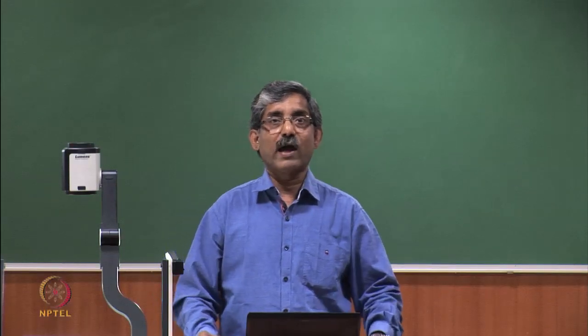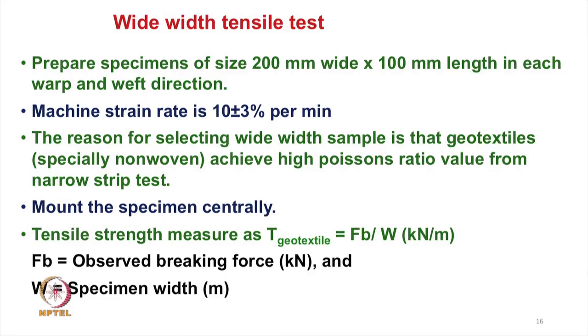First, we will discuss the wide width tensile test, where we must prepare a specimen of size 200 millimeter wide, so 20 centimeter wide, and 10 centimeter length in each warp and weft direction.